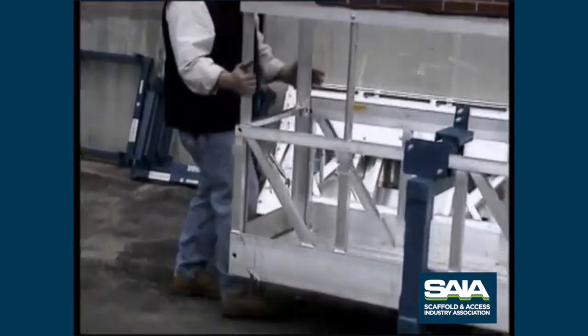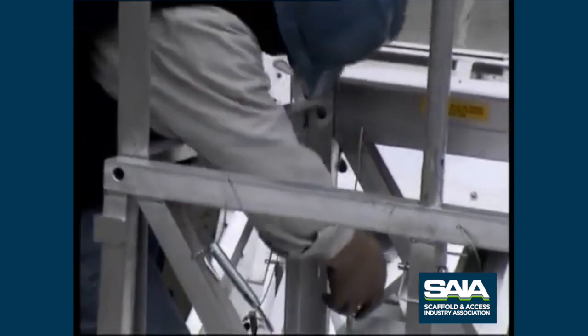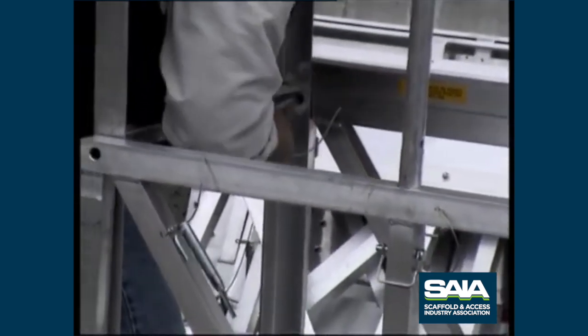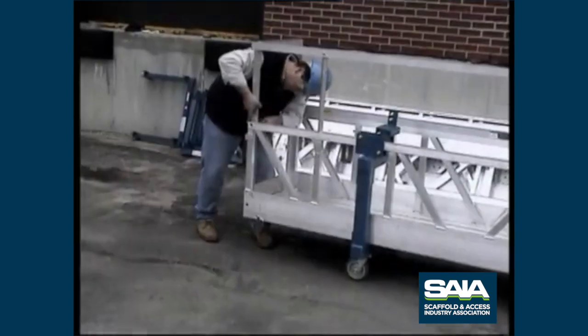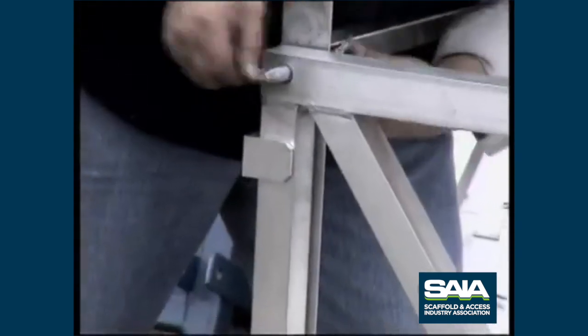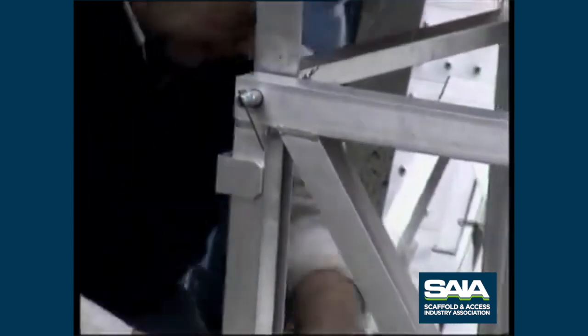Confirm that A-frames are not damaged and that all bolts have double nuts or cotter pins to keep the nuts from backing off. Most modular platforms have built-in guardrails and end stirrups. If using a walk-through stirrup, always use end guardrails. Always check with the manufacturer for proper configuration and assembly.